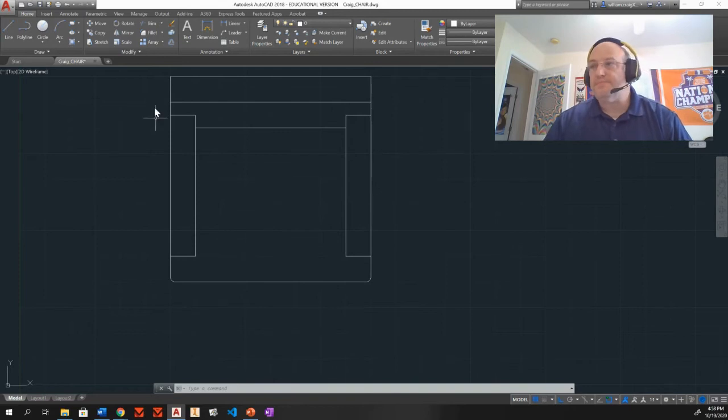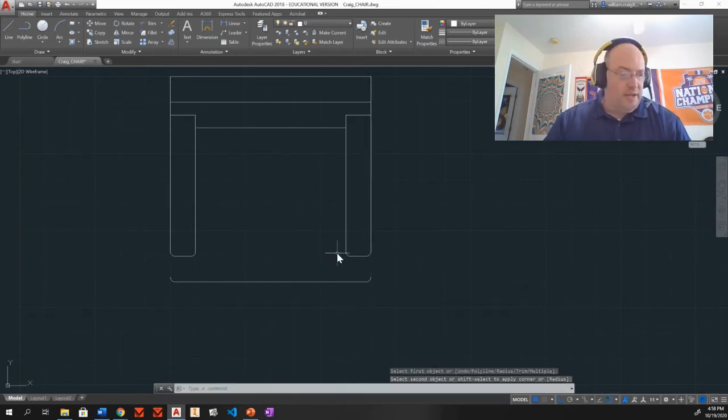Now let's do the arms. So I'm going to grab fillet. I want to grab here. So now I have a nice little rounded corner there. I'm going to go fillet here. Do those two. Nice little rounded corner there. Very nice. And then I want to go ahead and round off this spot here too. This is where things are going to start going away from us, but that's fine because we've adjusted for that. So I'm going to grab fillet. I want this object. I want the second object. And there it is. It's nice and rounded, but that line went away. Don't worry about that at the moment. We're going to get that back. So once again, we'll do it to the other arm. And there we go. We now have our arms looking nice and pretty.